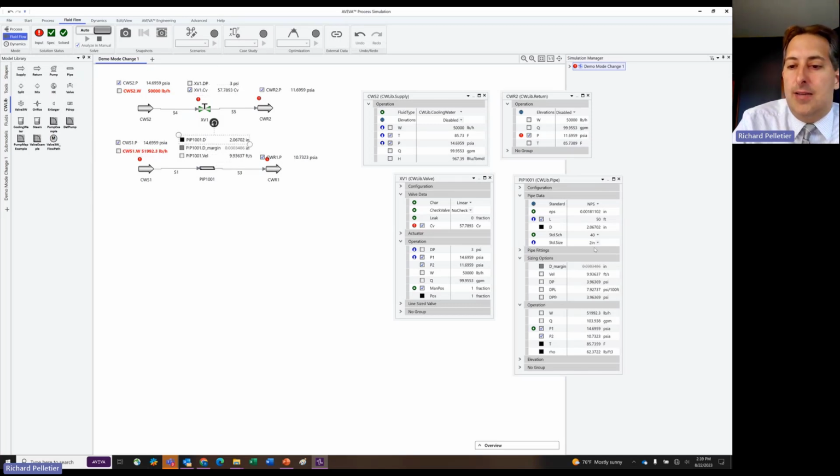It's technically this size parameter that's specified. And instead of the things that were specified before, flow rate, pressure drop and velocity, those things are calculated in this case. So switching modes swaps around the specs to meet the purpose of the mode, rating the sizes that we previously calculated.